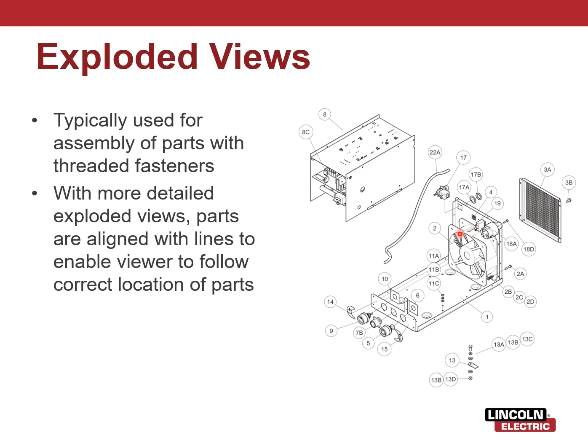This gives you a good reference of all the parts that go together and the direction that they go together. This is also usually where you find references, like you see in here, where you can explode it and say, if you need to replace this fan, you could go reference number 2 in the book and it should give you the part number and all that good stuff. So exploded view is very useful, very common.